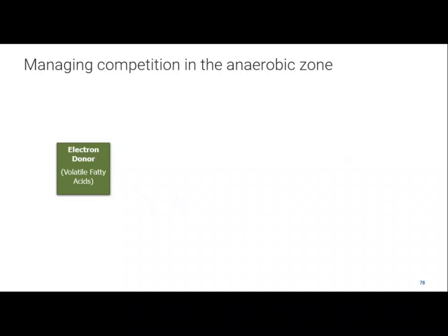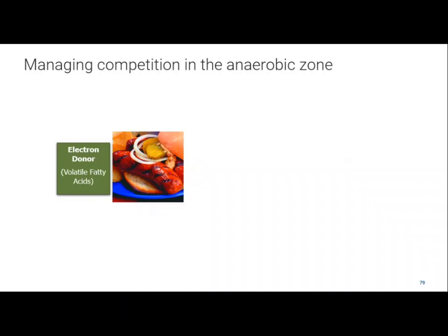I'm going to give another angle for it. This is an analogy I've used before. I know Rodell really likes it, so we just keep using it year after year. So what is VFA? When you're thinking about trying to keep this competitive advantage for our PAOs, what we want to give them is the volatile fatty acids. And we talk about volatile fatty acids a lot, and really that's the best piece of our wastewater. It's the best fraction, right?